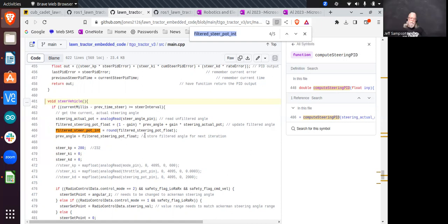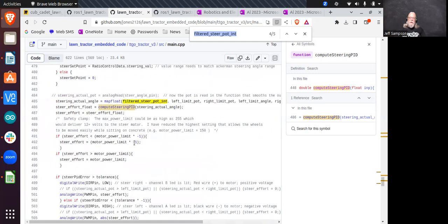So you're talking about your code somewhere where you say do PID or whatever, and that's going to return a value back to you. That's going to be some power value. Before you pass that power value on to your PWM generator, that's where you want to check it. Check your steering and see if you're too far one way or the other, then don't just pass that number through. Just pass a 0 instead. Maybe down here where it says that, yeah, you're doing.